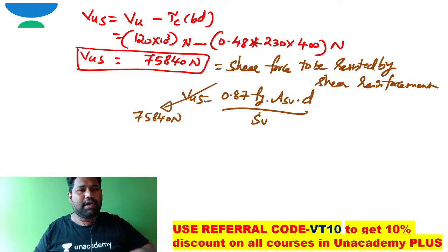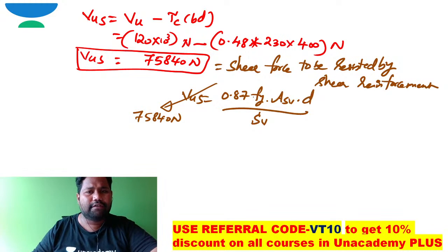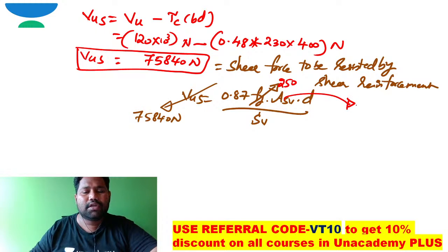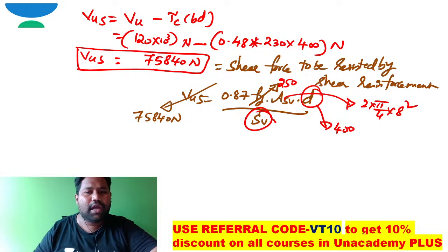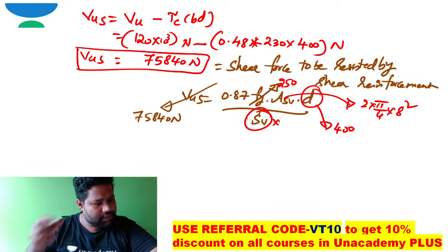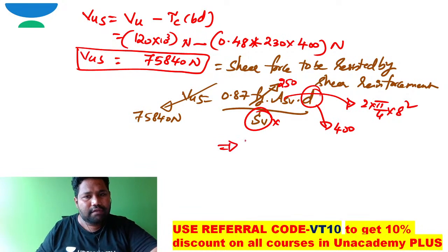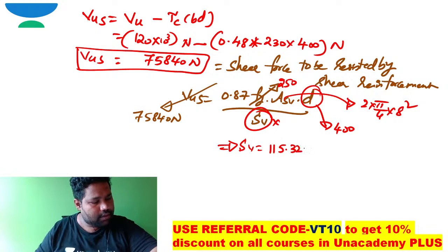Fy, the yield strength of the shear reinforcement, was given as 250 megapascal because it is mild steel. ASV is 2 into pi by 4 into 8 square, and effective depth is 400. The one and only unknown is SV, which works out to 115.32.